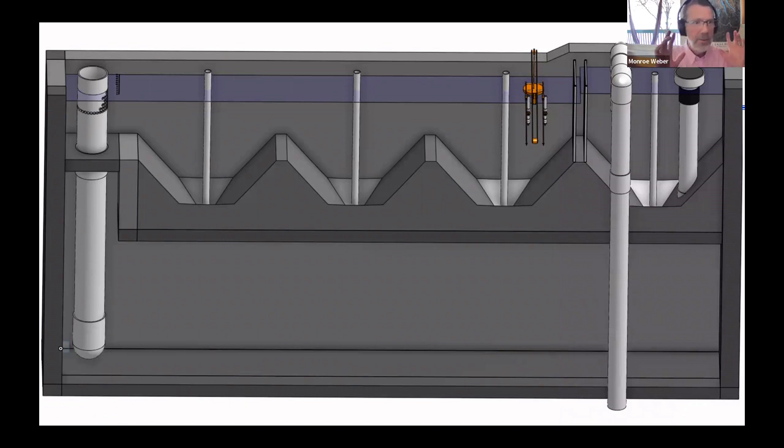And to be fair, we're going to talk about sedimentation, I don't know, 4 weeks out or something, but it's not so complicated. You can just remember now that the trick for sedimentation is that the only thing that matters in a tank is the plan view area. So all that matters is the plan view area. That's what's going to determine how much sediment is able to be removed.